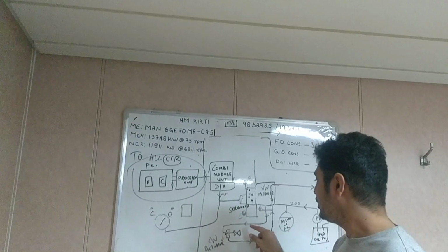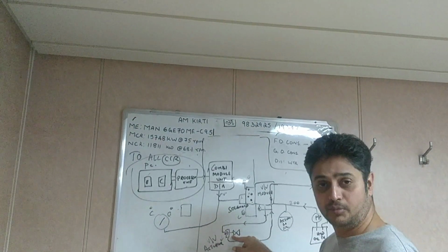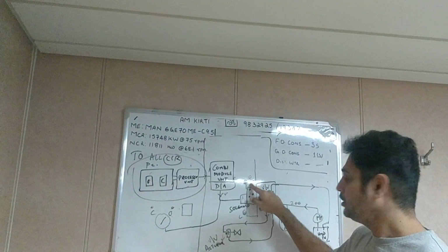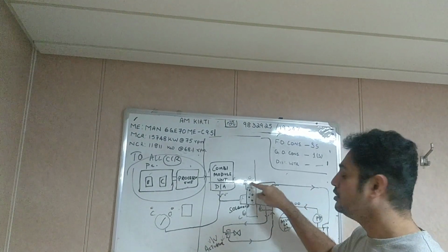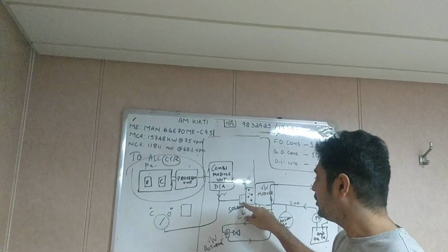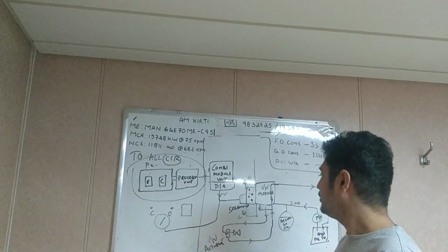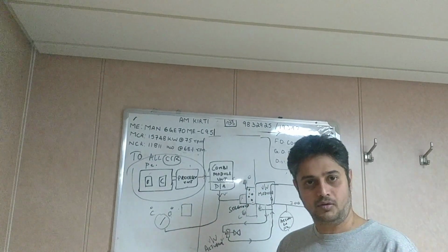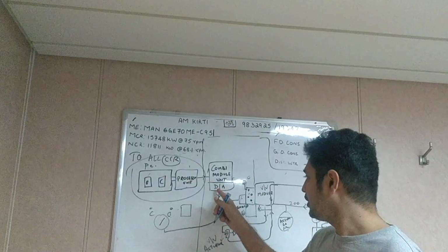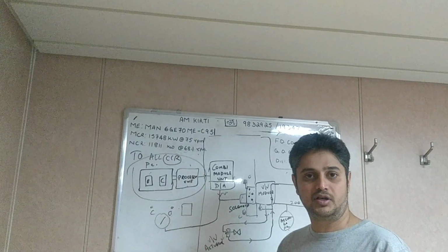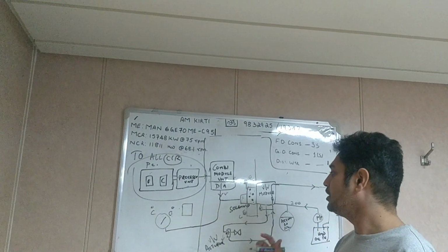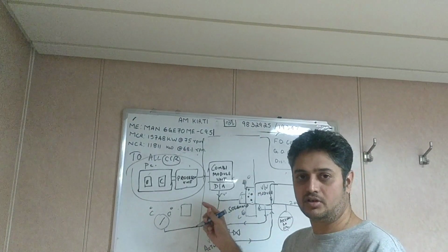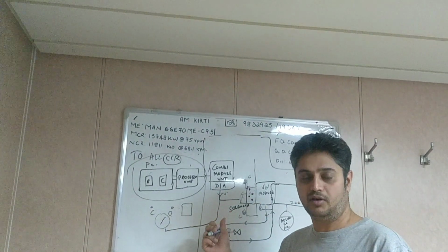Once the solenoid is energized, if there is no response here even after energizing it, try to operate it manually. If it is working manually and only not working with the solenoid, then something is wrong in this spool, so you change only this block. If the solenoid itself is not getting energized, see whether replacing it with a new solenoid changes how the system works.